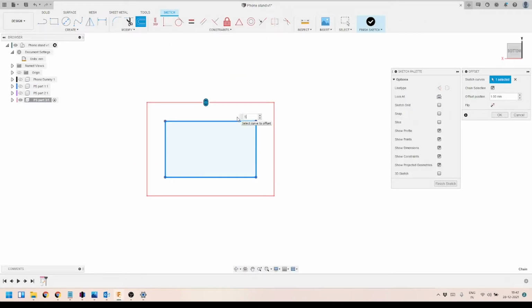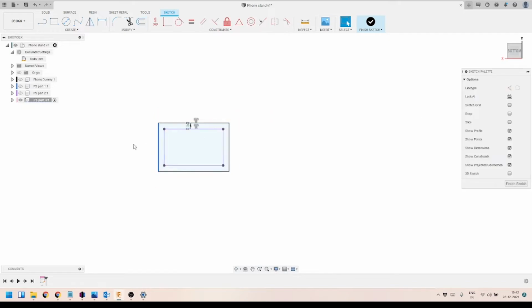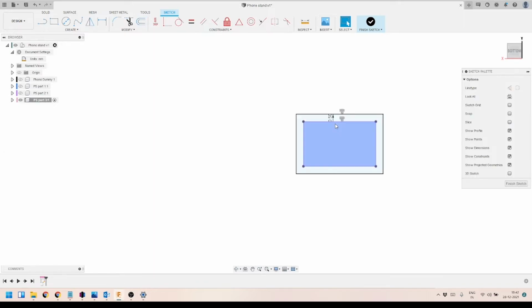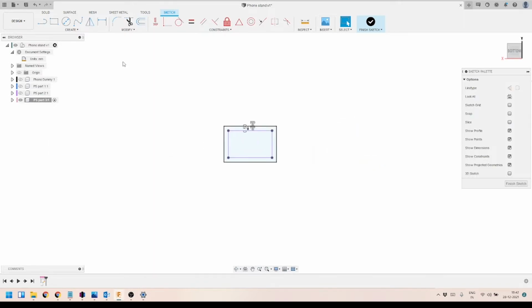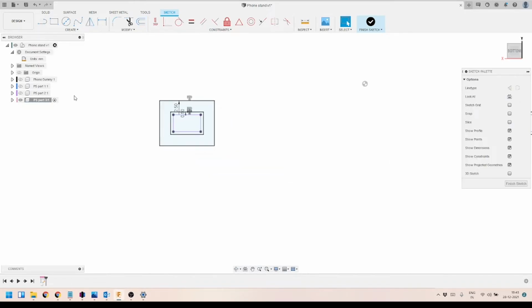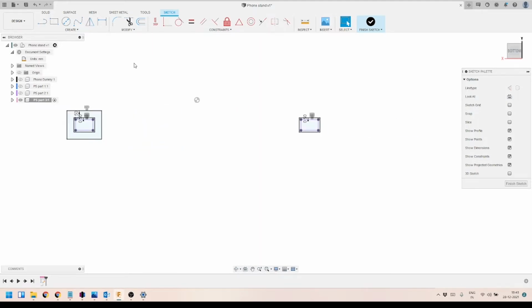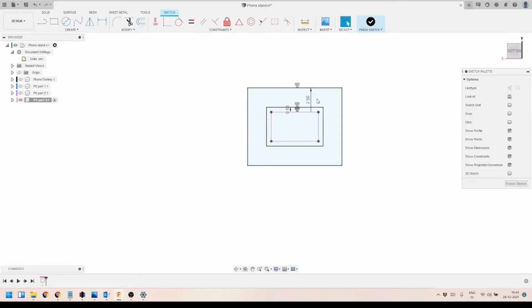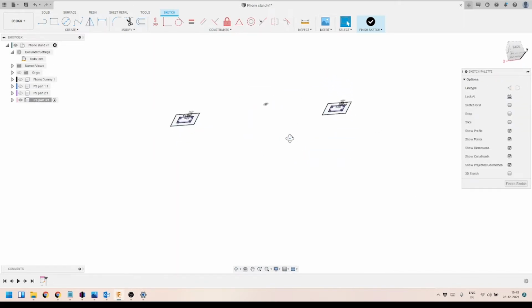So we'll use a tolerance of 0.5 millimeters on both sides. For that we are using the offset tool to create a tolerance of 0.5. Next we'll apply the thickness of that part, so we're going to create it as 2.5. The thickness is 2 millimeters since the offset is 0.5 here already. So this way we can create the thickness. Here you can see 2.5. Here it is. So this is how we created it.